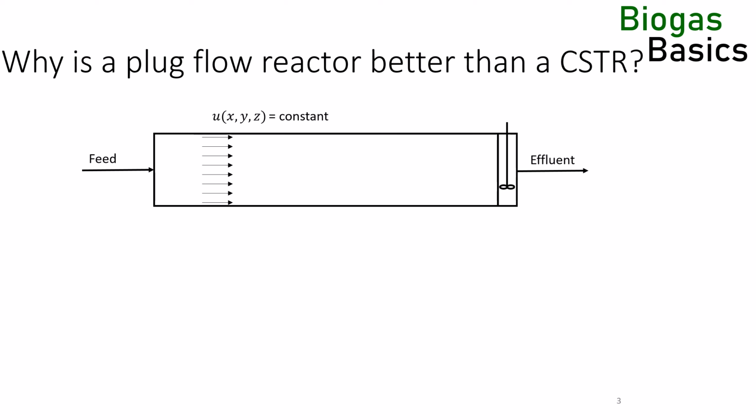At the end of the batch, or at the outlet of the plug flow reactor, after all, a plug flow reactor is a batch reactor where the time axis has been exchanged for a spatial axis. The substrate concentration and the reaction rate are low, lower than that of a gradient-free continuous reactor of the same size. Therefore, the plug flow reactor is more efficient than a continuous reactor regarding substrate conversion. However, it must be able to maintain its substrate gradient.